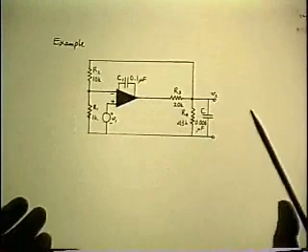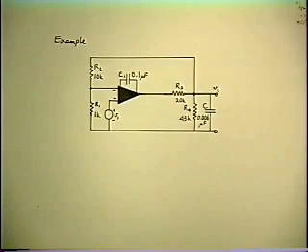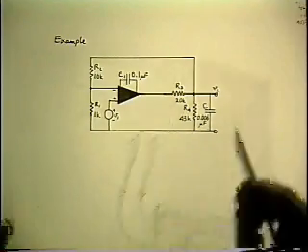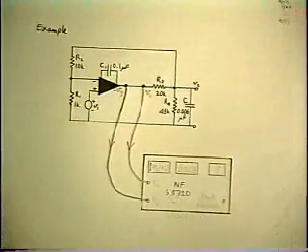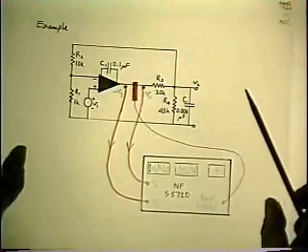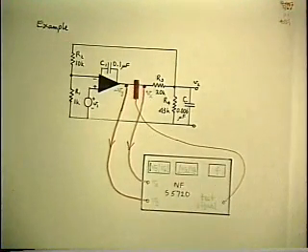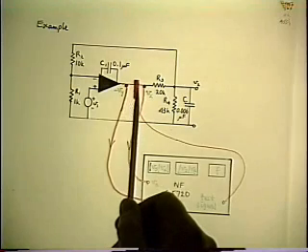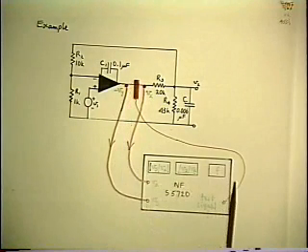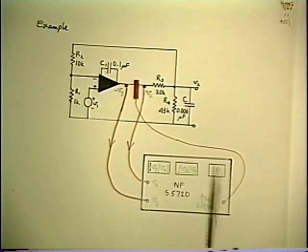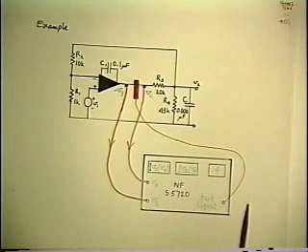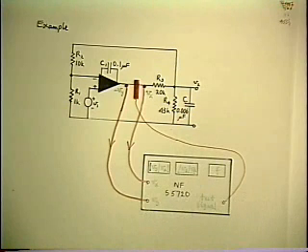However, it turns out you do have an isolation injection transformer handy all the time. And it's called an AC clip-on current probe. And that's all it is. It's a transformer, except normally you're supposed to use it to measure a current. What you do is you clip it around a wire whose current you want to measure, and you put the other end of it into a termination or an amplifier, which converts the measured current into a corresponding voltage, and you can then read that on a voltmeter or an analyzer or whatever you like.